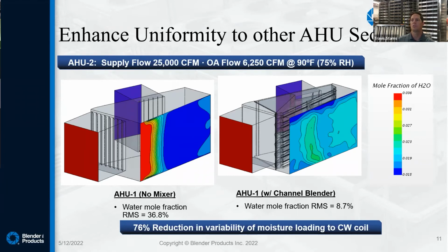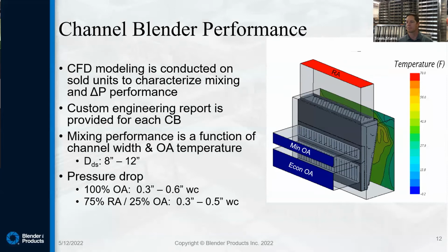So we're trying to quantify in dollars and cents what that means for some of our clients, so we're continuing to work on that value proposition. Every one of our channel blenders is subject to CFD. The reason for that is we want to provide our clients the surety and the data to know that freezestat alarms can be eliminated during operations during cold weather events. That's what we're after, and that's what we design around.